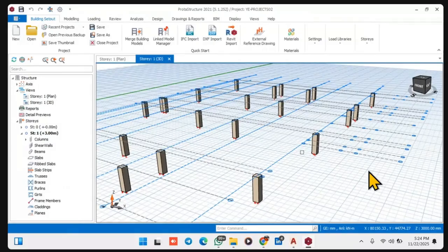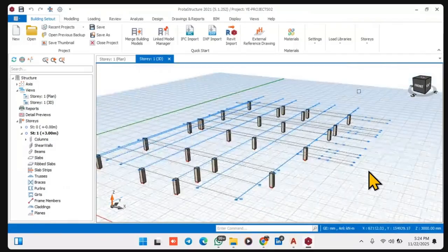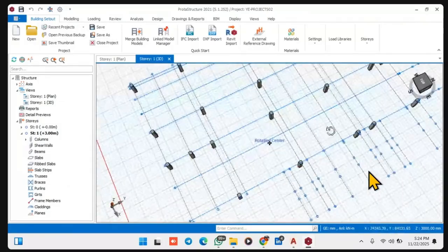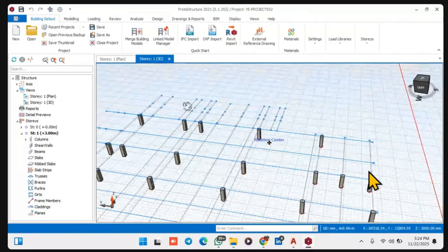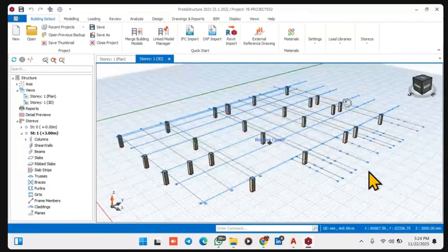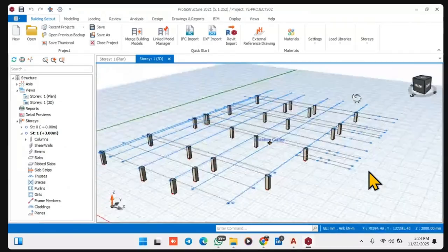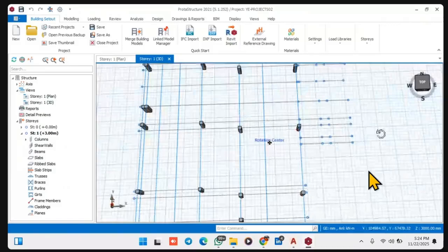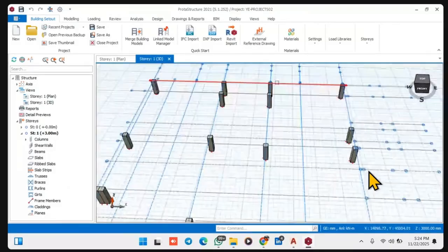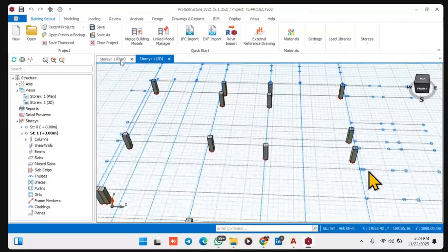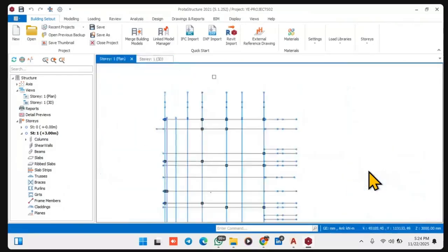Yes, sir. So I can manually put in my this thing. You know why they are coming with a lot of grids? It's the level of preparing the model. If the model is not well cleaned, sometimes it can come with extra grids, like here, I can see these grids on the right side. Let's try and delete the unused axis.